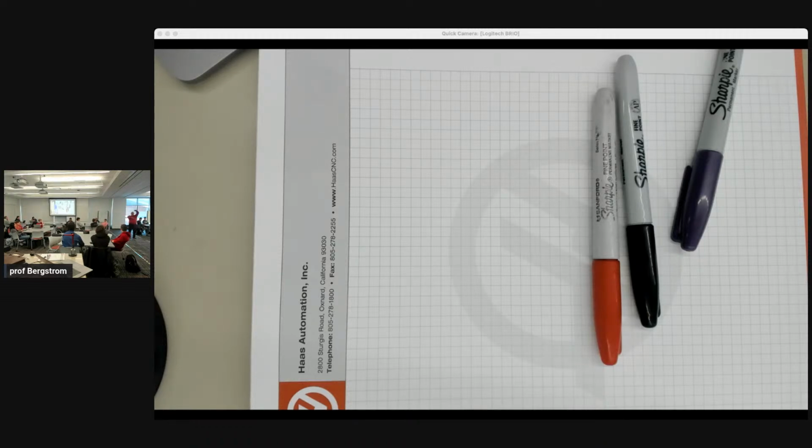When it's far away, it's hard to do the visual estimate. But you could press the stop button, stop the spindle, reach in and get a tape measure and measure it. You could do that. I usually wait till I can eyeball it to be about an inch away. I feel like I can eyeball that inch distance. And this is why we reduce the rapid speed. On the mini mills, I'll use like 25%.